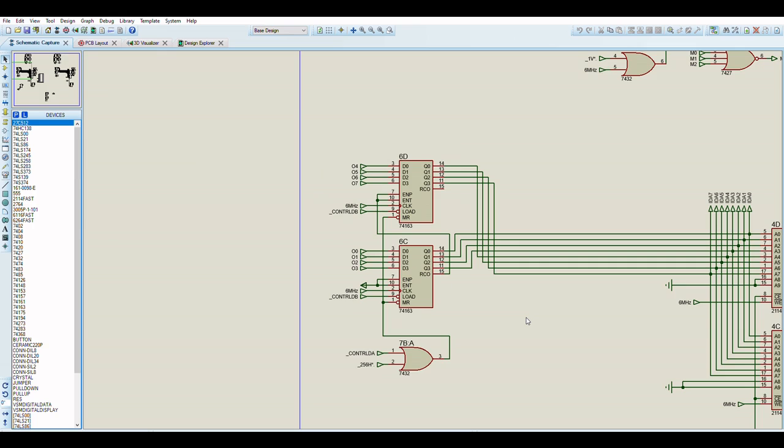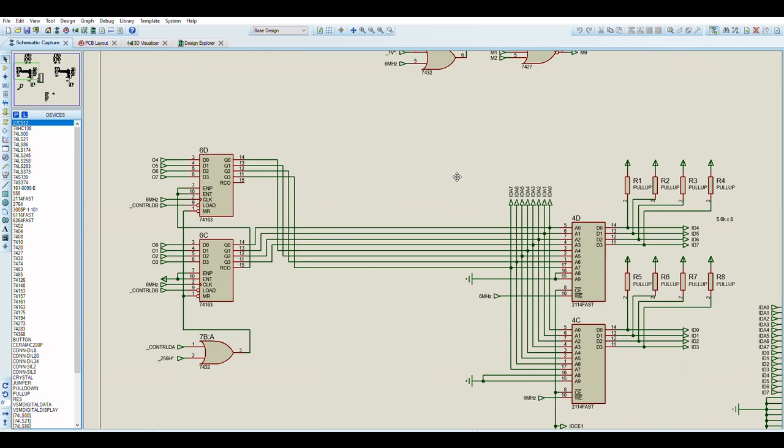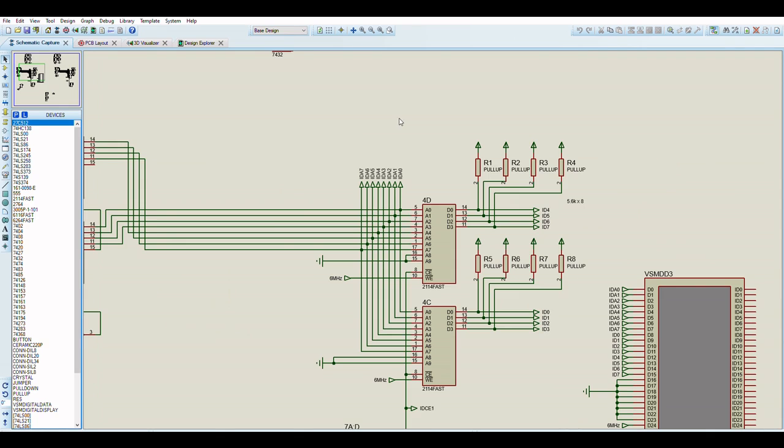The data in the scanline RAM is first read. So either these two RAMs or just this one RAM, the data is first read when the inverted 6 MHz is 0. And the output value is then clocked.